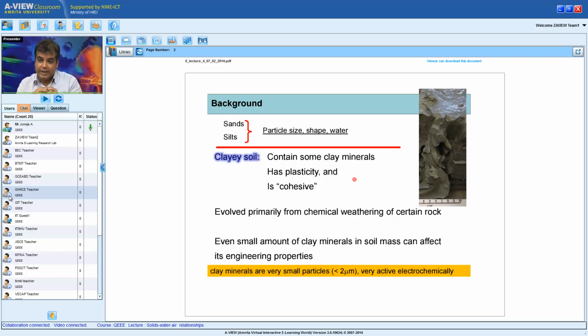Now for the last 2 or 3 decades, that's about 30 years, there is a small group of very strong researchers who have started to realize that I call clay cohesive, but I can also do an undrained triaxial test on sand and get a cohesion value. So in other words, can I also call sands cohesive because it's pure cohesion?